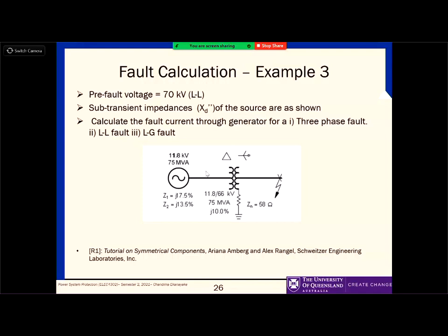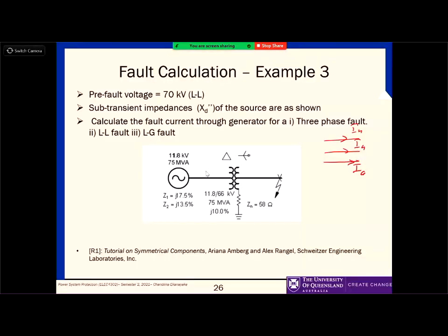If you have, say, 3 lines, IA, I will write the same magnitude of the current is going through, right? So let's say it's I0, because it is the zero sequence current, and then this connects to some sort of a box here. Nothing comes out, only these 3 lines are connected to that box.